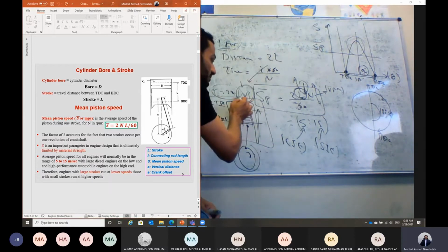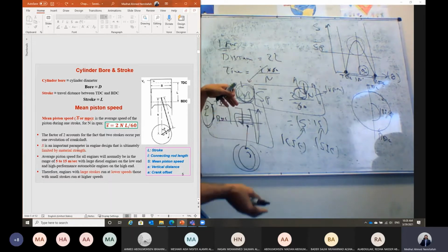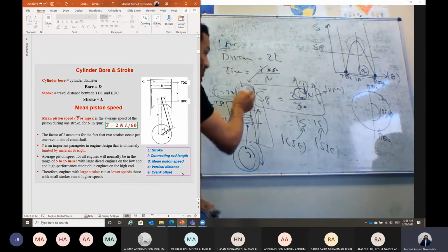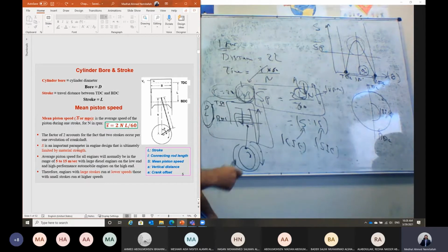So we have a high pressure value contained by the clearance volume at the end of the compression stroke. When the piston moves down, the pressure will be relieved and we can generate shaft power. But the pressure is very high, so we need the piston to travel a longer distance, so we can benefit from all of this pressure. It is related to the efficiency of the diesel engine, that it should have a bigger stroke, so that we have enough time for this pressure to expand to atmospheric pressure, then we can generate it in terms of shaft power.